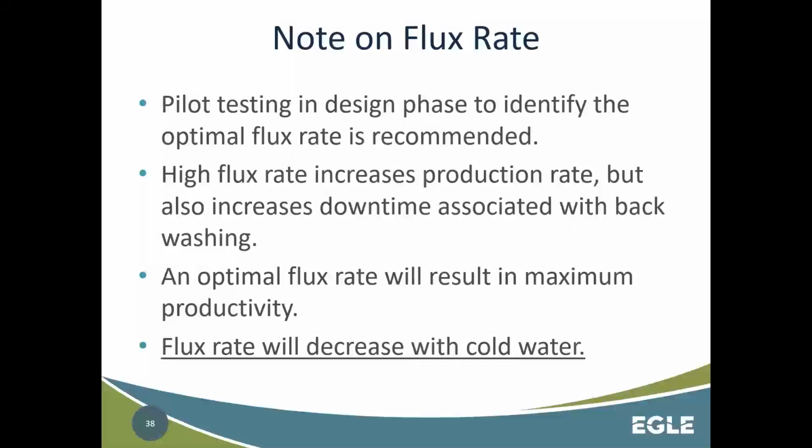Okay, note on flux rate. Again, hint to you test takers, flux rate is one of those glossary terms you should be aware of. I would say flux rate for membrane filtration is analogous to your filtration rate for conventional filters. The industry has a different unit.